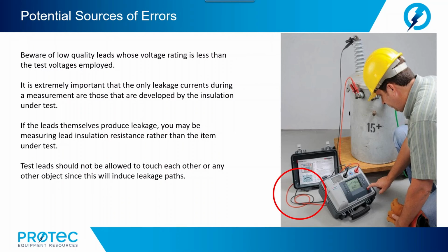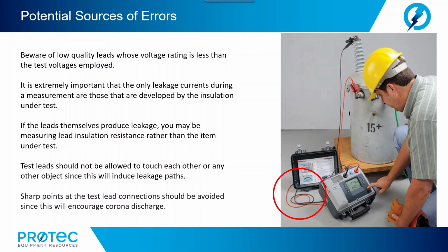Test leads should not be allowed to touch each other or any other object, since this will induce leakage paths. Sharp points at the test lead connections should be avoided, since this will encourage corona discharges.